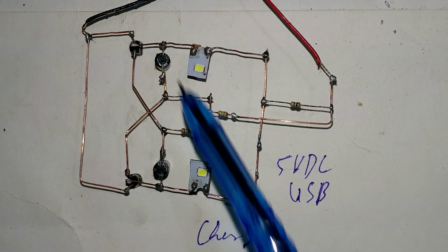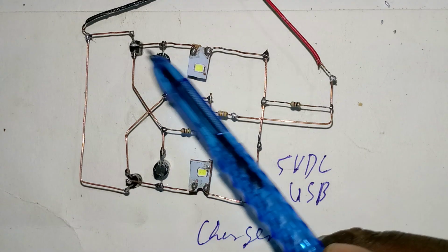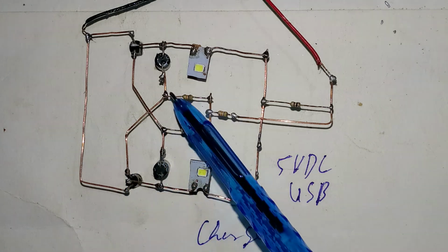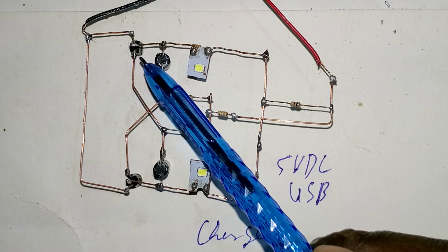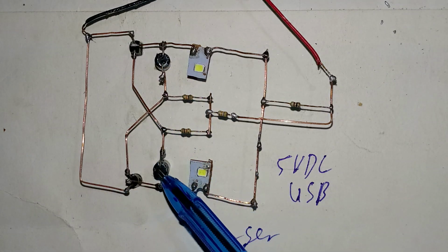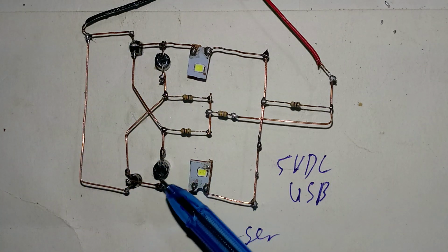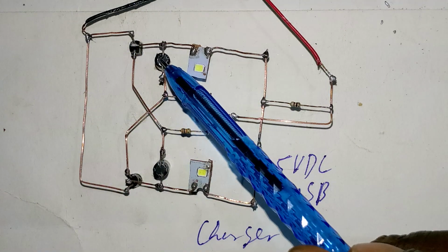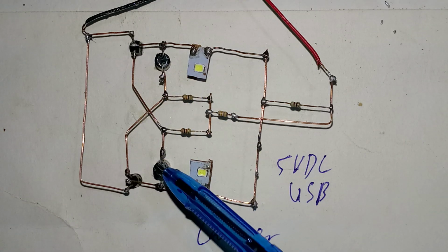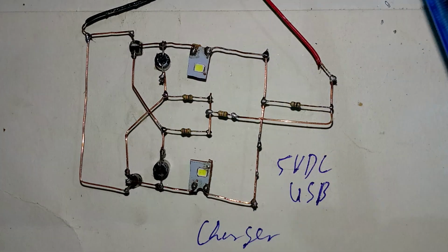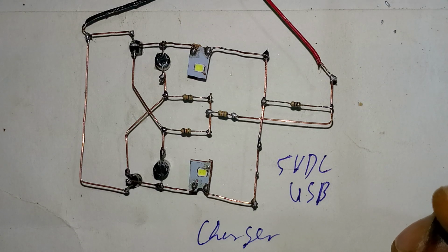Now you can see both leads, you can see the capacitor. The capacitor is connected here to the base, and the negative terminal of this other capacitor is connected to this base. So as this is passing the current, the leads of both are connected through the resistance. So as this is discharging, this is charging. As this is charging, this is discharging. So that is how a multivibrator operates. Now let me power the circuit so that you will see exactly the action of a multivibrator circuit.